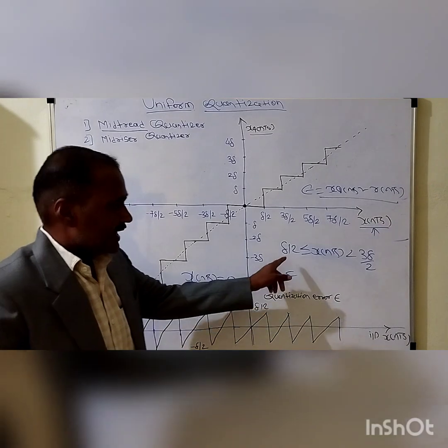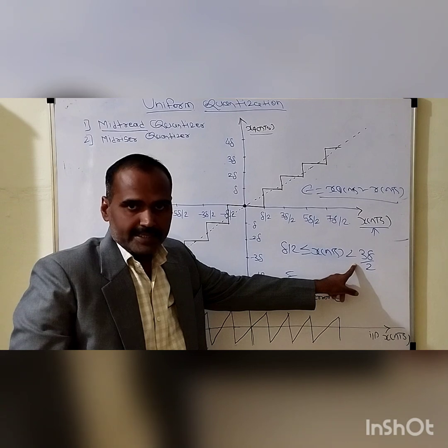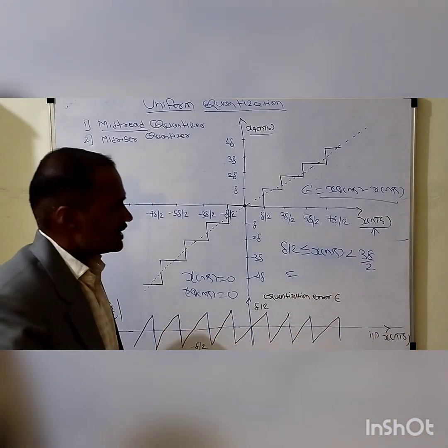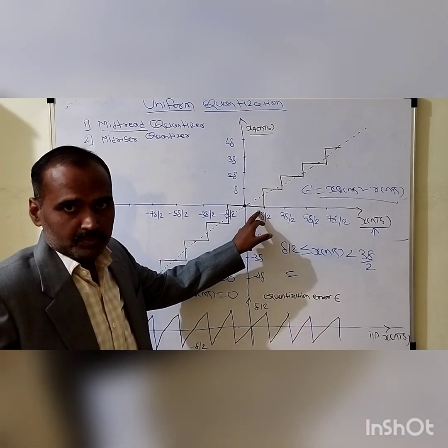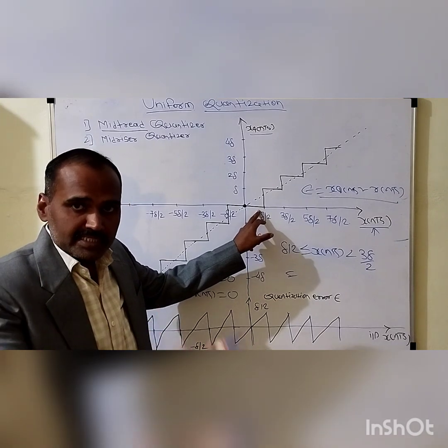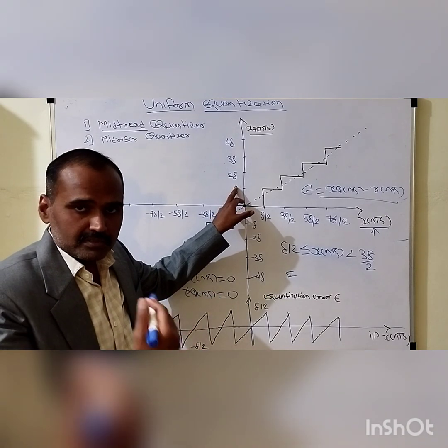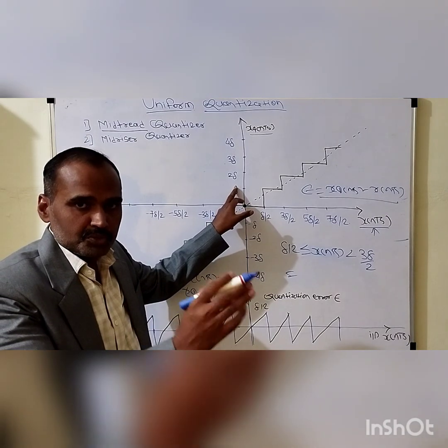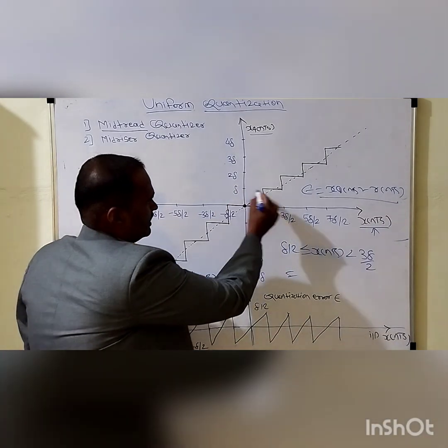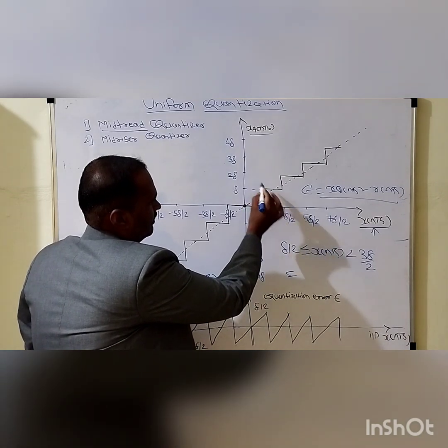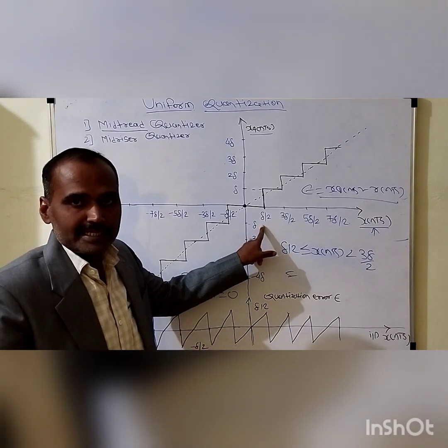when this x of nTs lies between plus delta by 2 and plus 3 delta by 2, or initially when it approaches plus delta by 2, which step size is selected by the quantizer? It will try to assign the nearest quantization level, the nearest threshold to the current sample, which results in minimum error. So it will assign the quantization level delta when the input is approaching the first positive value,